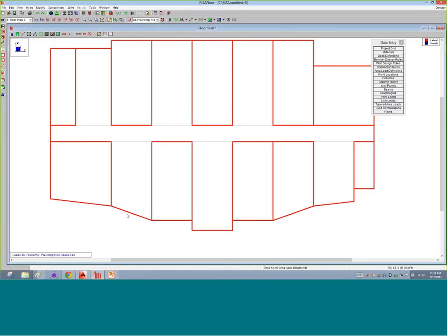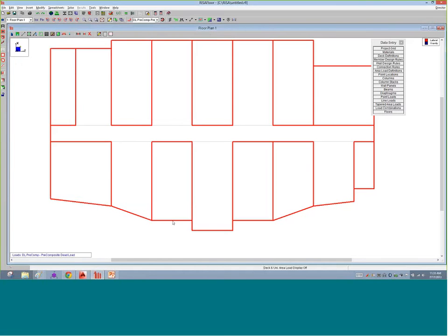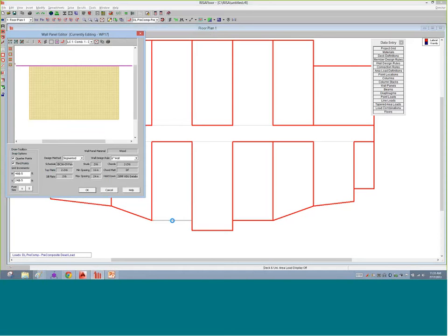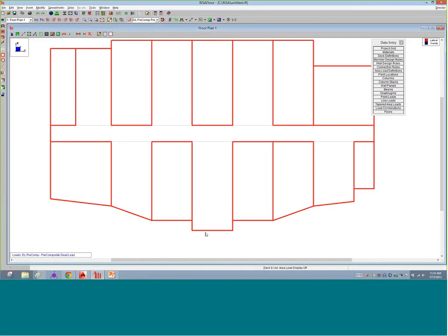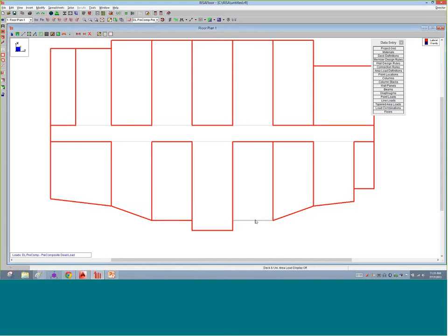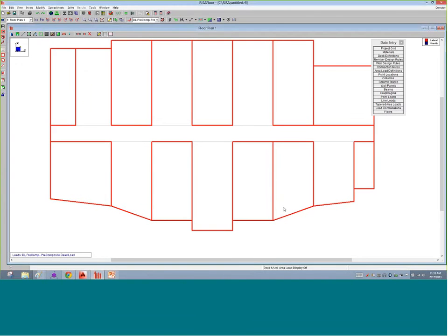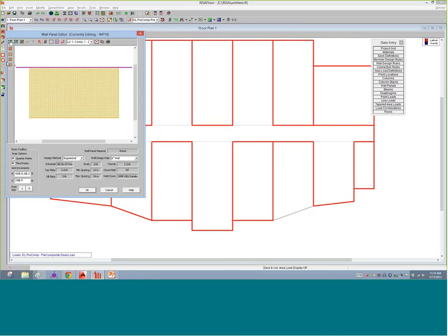The second wall, let's double click on this skewed one and draw in an opening in here, and let's create this one as perforated. And I'm going to say okay, and the next one I'm going to do is force transfer around openings. So we'll have 3 examples for us to work with, and we can think about how those will work. I'm going to drop a couple more openings. Those are sort of window openings. We'll drop in some door openings, and this is just a nice example for you guys to see how the openings are going to be treated in our models.